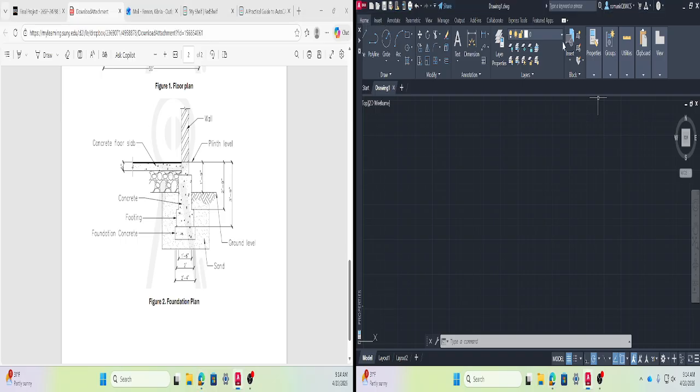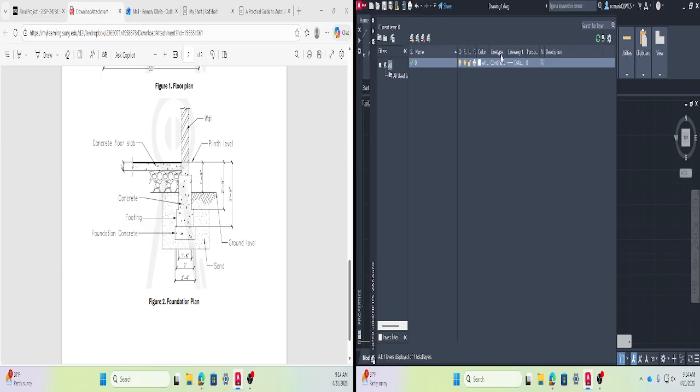let me see, layers, so several layers here. You go to layer properties. I don't know if you can see this. Okay, yep, now you can see it, and you can basically define several layers for different materials that you're seeing, like for concrete one layer, for this wall another layer, right? For sand another layer, ground another layer. So you'd like to define all those layers, right? And you'd like to draw this structure that you're seeing here first, for the foundation, and later assign all those different layers to these different sections. Okay,